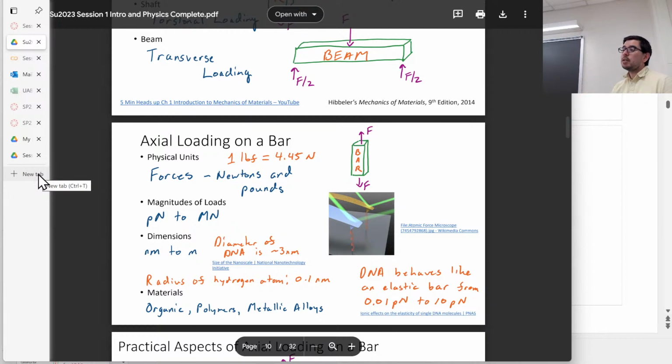But another factor is that you can change the concentration of dissolved air in the PDMS by applying vacuum. So that means that as a bubble is formed and there's surface tension that causes there to be high pressure inside the bubble, it actually creates a gradient in concentration, which causes the bubbles to collapse, okay? Because it goes from high concentration in the wall of the bubble to the surrounding solution. And so the bubbles will actually get smaller just by changing the concentration.